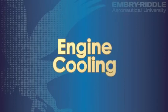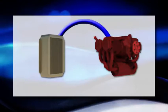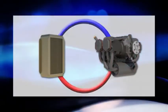Like car engines, airplane engines have a cooling system in order to prevent engine damage or engine failure. There are two major ways we cool our engine: oil and air. Oil passes through an oil cooler and proceeds to not only lubricate, but also cool the engine. As the cool oil touches the hot engine, there is a heat exchange, meaning that the oil becomes warmer, but the engine cooler. Then the oil returns back to the oil filter and oil cooler, and the process starts over.